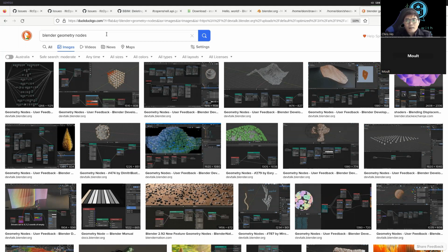What's important in BIM is that you have a wall. Whether that wall is a rectangle, a mesh, a solid, an extrusion generated via nodes or not generated by nodes is secondary to the fact that you have a wall. And so you can hook up a variety of, I guess you call them, geometry generators. It doesn't matter what you use. At the end of the day, you can always plug it in as a geometry to be connected to an IFC object.